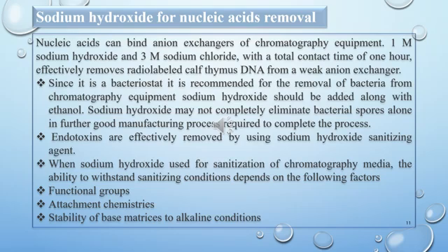Till now, we have discussed sodium hydroxide is being used for the removal of protein. Then we have discussed that sodium hydroxide is being used for the removal of nucleic acid. How? When we use the 1 molar solution of sodium hydroxide and 3 molar solution of sodium chloride, then we can remove nucleic acid from chromatographic equipment.